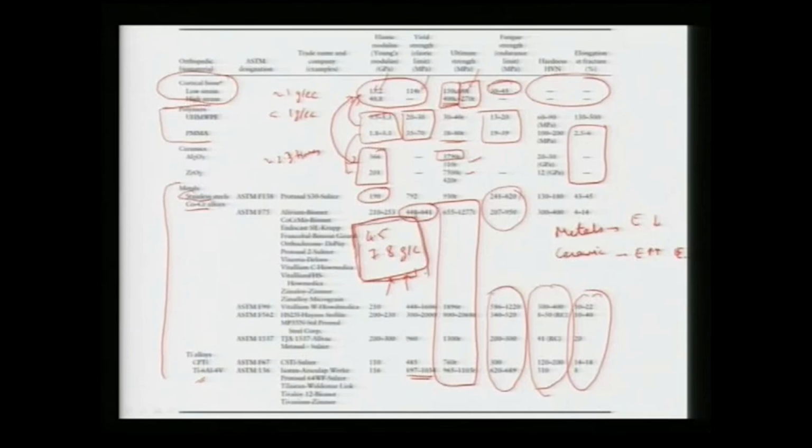So we can see metals are highly tough, and they have a very high elastic modulus, which can lead to stress shielding of the bone. So generally these metals are now coated with porous ceramics, and porous ceramics generally have densities on the order of 2 to 3 times that of cortical bone. So porous ceramics can really serve as a material similar to cortical bone.